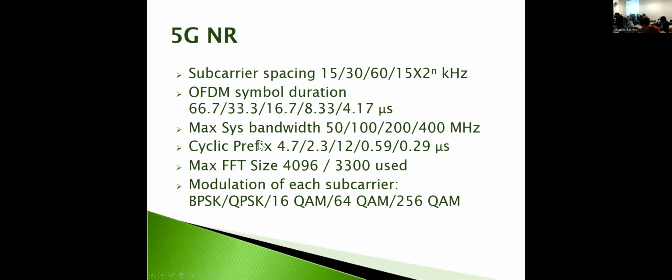Remember, this helps us decode this without having to do all this crazy equalization or compensation of our waveform, but it also is wasting time and energy. So we don't want to go too long, but it needs to be long enough to cover that delay spread of reflections from the minimum delay to the maximum delay.